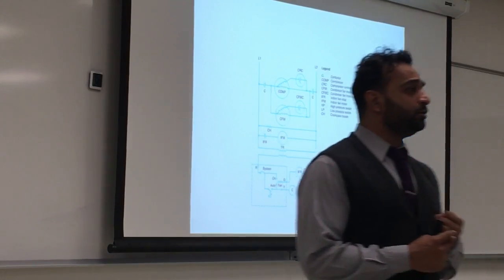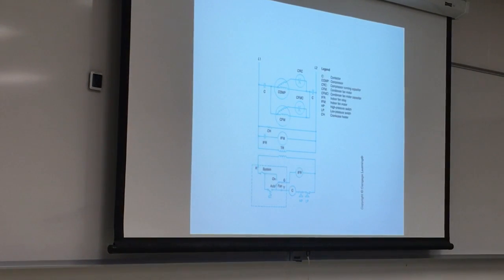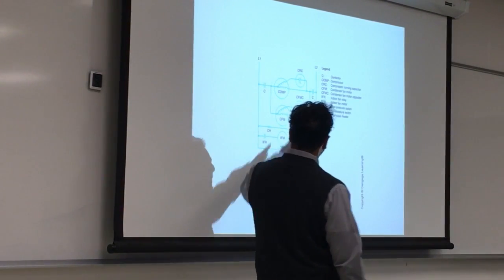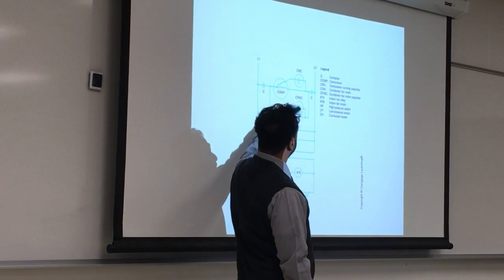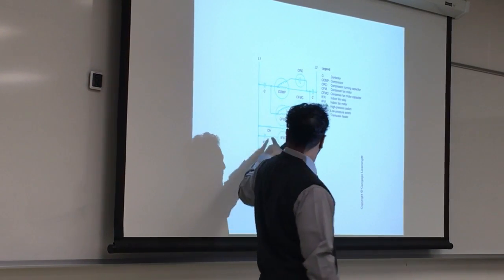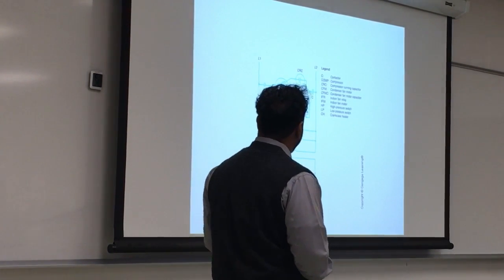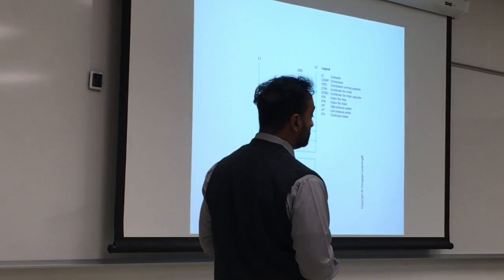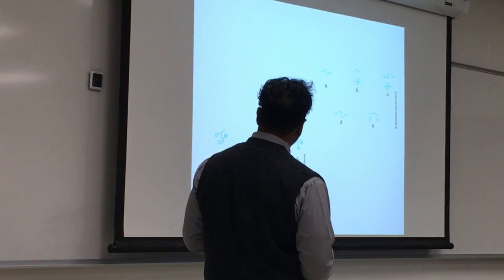Again, the first thing you do when you look at a schematic is what? Don't freak out. Do not panic. You know all the components, you know the line voltage. Go and write down on it what you think this is. Even though this is very simplified, I don't even need this wire inside and I don't need these lines. This is maybe a little too much information, but if I just look at the wiring, it should be consistent.